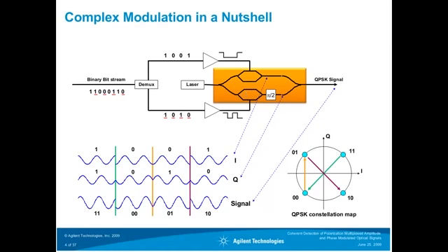So, looking into detail at what is coming out of the first Mach-Zehnder structure: in the case of a 1, there's a cosine phase. So you start up here and go down there. And then if you switch from the 1 to the 0, there's a 180-degree phase shift. And if you stay from the 0 to the 0, there's no phase shift down here. And then if you switch from 0 to 1, there's another 180-degree phase shift up here. That's the upper arm of the modulator structure.